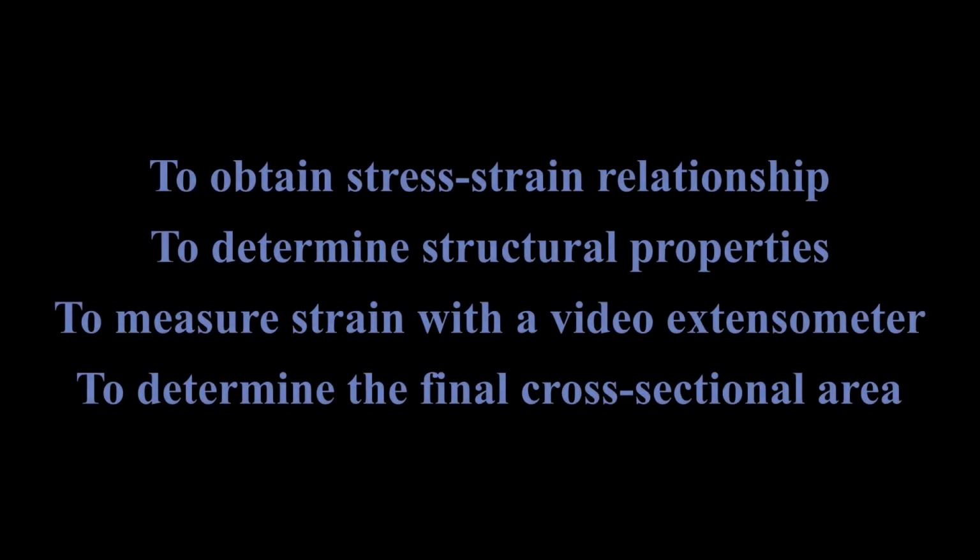The objective of this experiment is to load a tensile test sample at a constant crosshead speed until failure, while recording the value of the load and the change in length of the test sample at each stage. Then, based on the collected data, the stress-strain relationship will be obtained. Modulus of elasticity, yield strength, ultimate tensile strength, yield strain, failure strength and strain to failure will be determined.